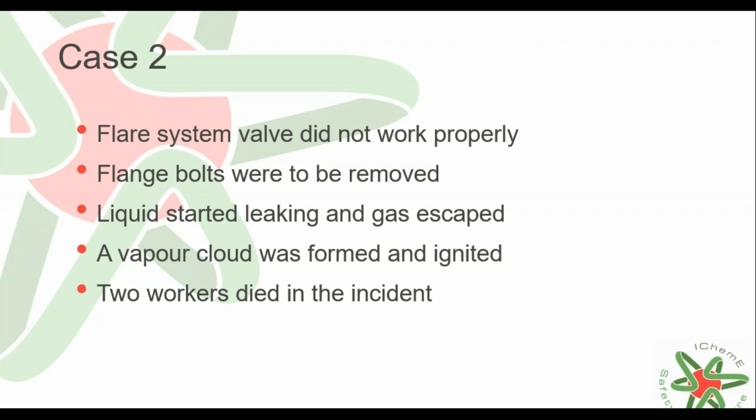Now, a cold work permit to work was issued 2 days prior to the incident. Alternate flange bolts were removed and the other bolts lubricated, as it was the standard practice to save time. Sufficient bolts remained at all times to retain the flange seals. There was, at the time, no need to verify line conditions. 2 contractors wearing breathing apparatus completed the work. When almost all the bolts were undone,